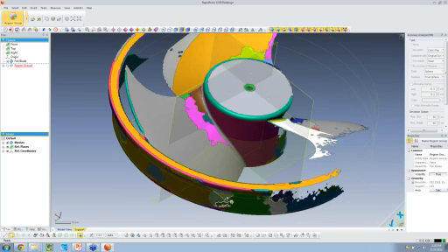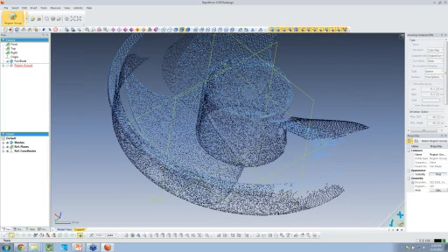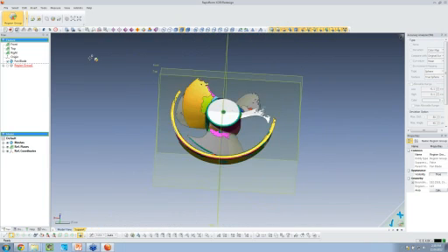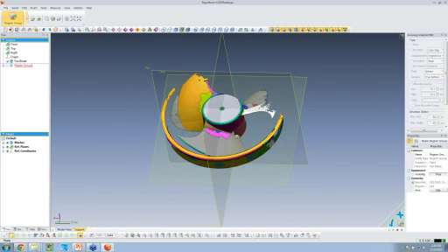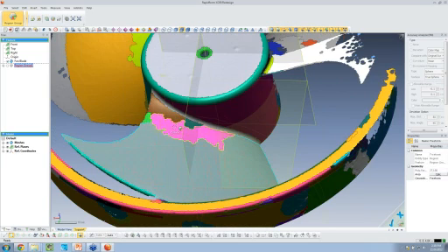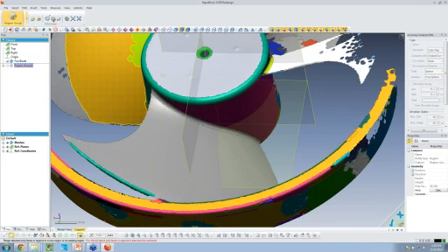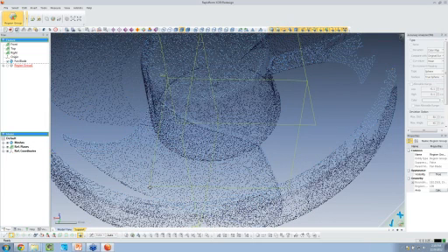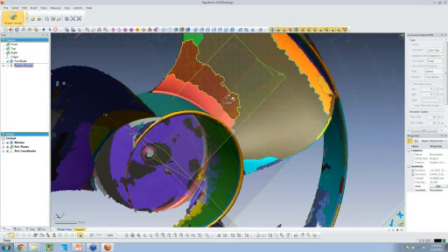So you notice the part, I'm going to start modeling this part. I don't have this part in its entirety. I can also append some of these features together if I wish. Say I want to make all these things part of the same region group. I have the ability to append this information together. Now I have a freeform surface that is much larger. And I'll do the same back here. The only reason I'm doing this is it just makes selection easier in a downstream process.